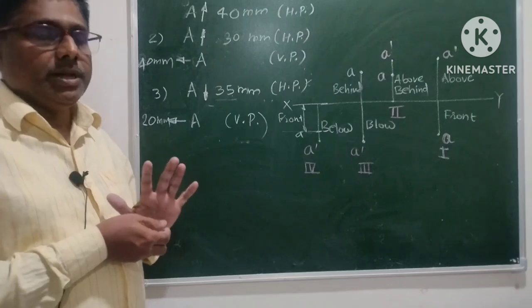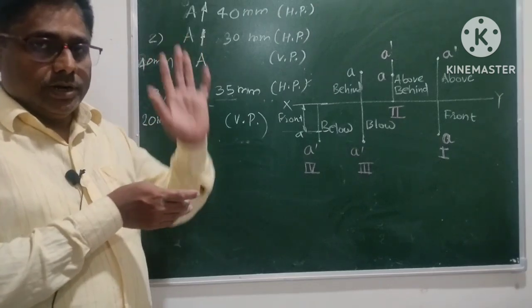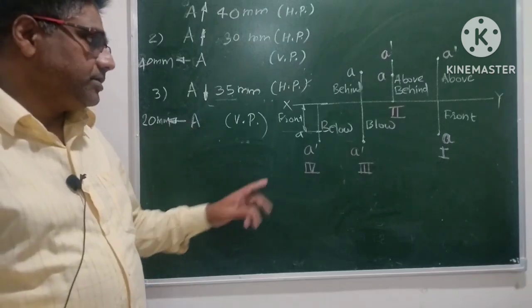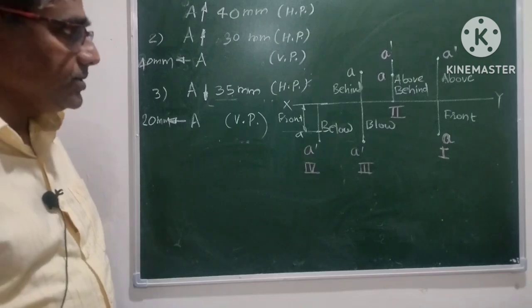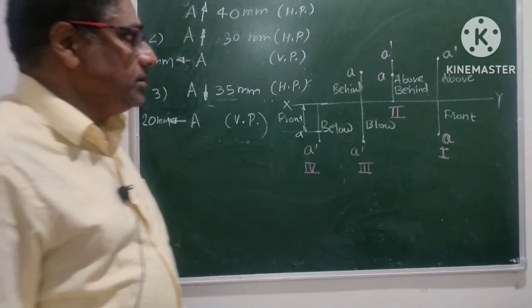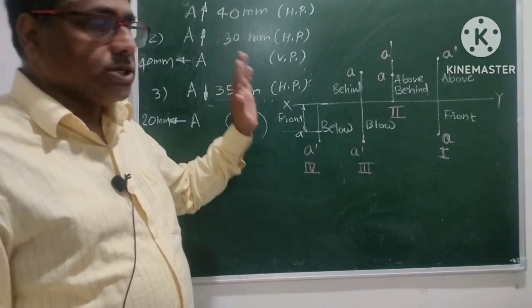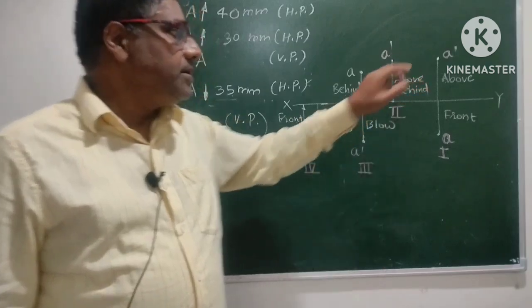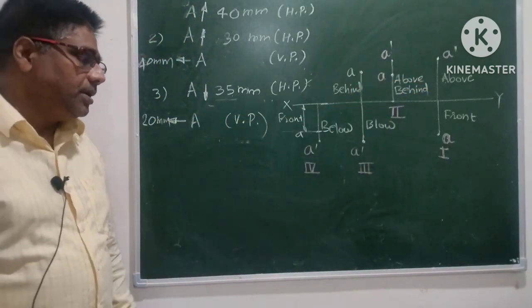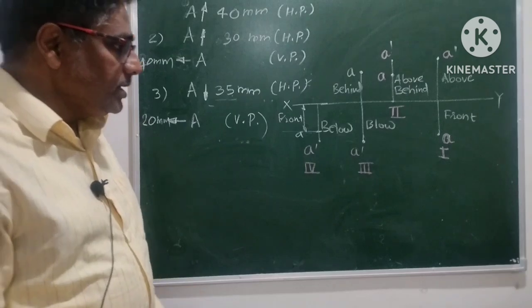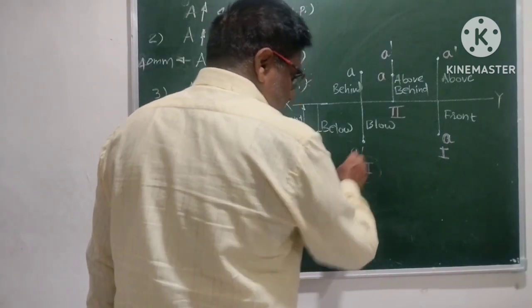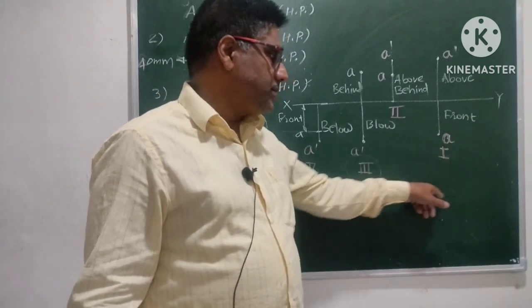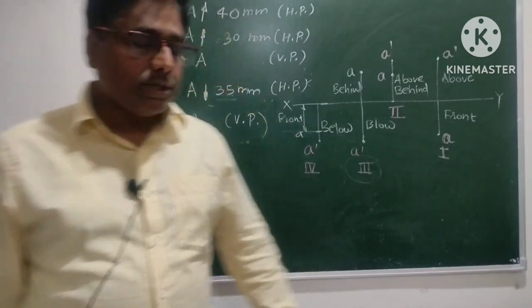After rotation of the horizontal plane, the frontal part of that HP and the vertical plane will overlap, and the two views get overlapped. The same thing happens with the rear part and the upper portion of the vertical plane, which will overlap in the case of the second quadrant, that is the second angle method of projection, which is not used. But the present scenario is, nowadays this third angle method of projection has been outdated. Now the whole world is adopting this first angle method of projection.